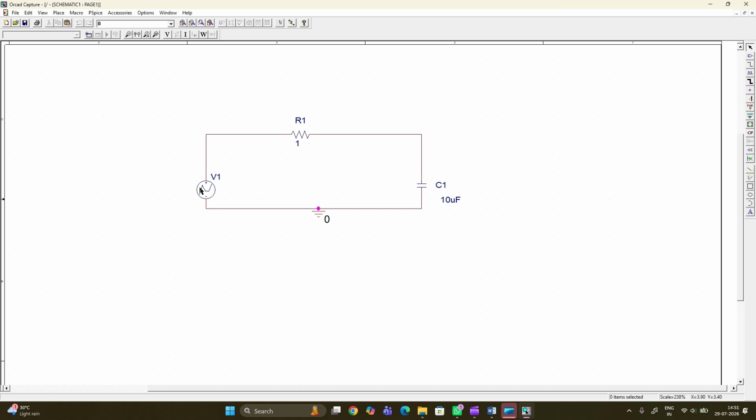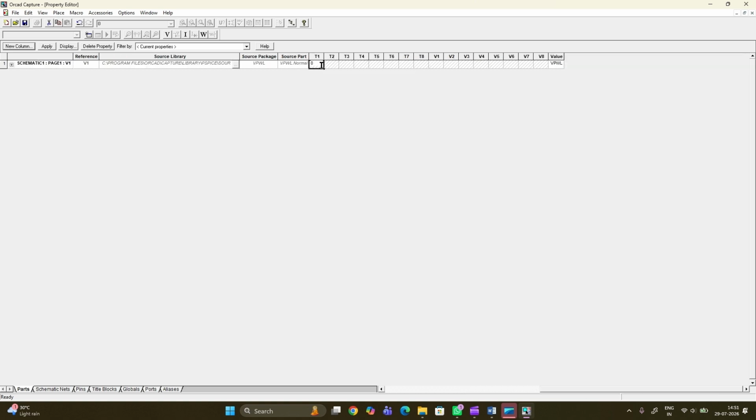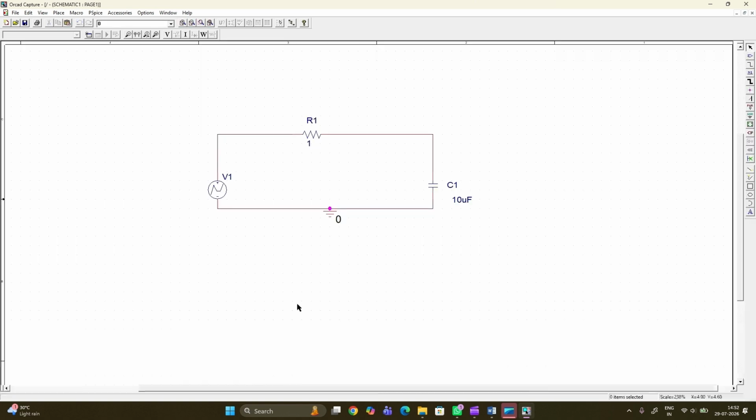Okay. So again, for the waveform I need to take the values at different time instants. So T1 0, T2 1 nanosecond. Next 1 millisecond, 2 millisecond, 3 millisecond. You can give up to 6 milliseconds if you want, otherwise you can complete it. So here I take 5 volts, 5, 5, 5, 5. However many time instants I have taken, that many voltages I need to take. We cannot give only T1, T2, T3, T4 without V1, V2, V3. You cannot leave the remaining columns empty, otherwise you will get an error. So you need to completely give the values for the given time intervals.